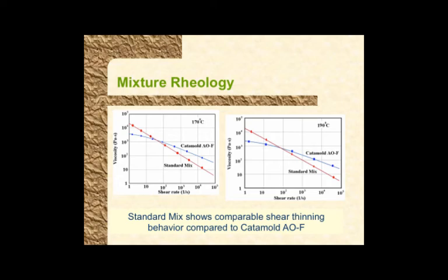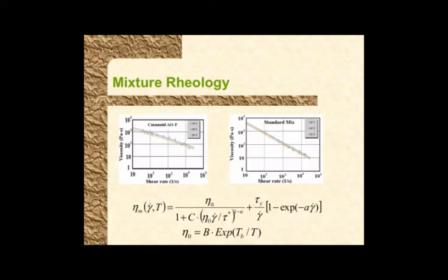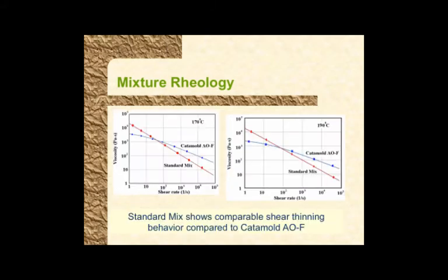So this is just a comparison at a given temperature, the differences in properties. There's a temperature regime where initially one is, the blue is the polyacetal, the red is the wax polymer binder. The main thing to note is you keep the powder concentration the same, but if you change the binder composition, your properties are going to be slightly different. The way you can make components is going to change a little bit, right? That's the main point. And the equation that we saw allows you to describe that mathematically.